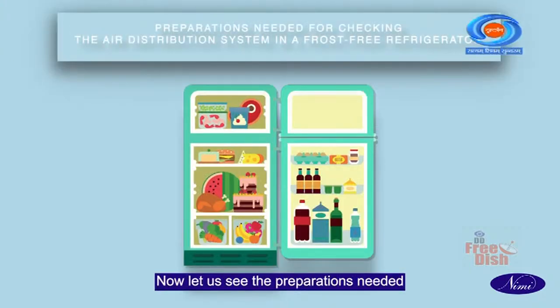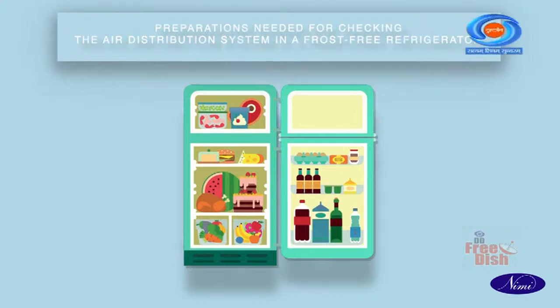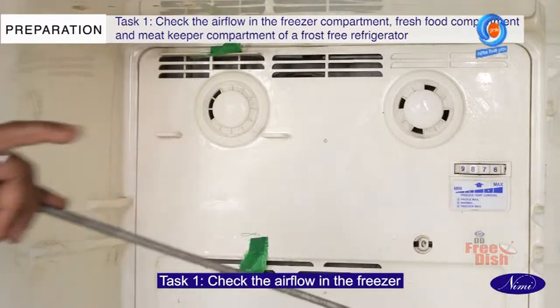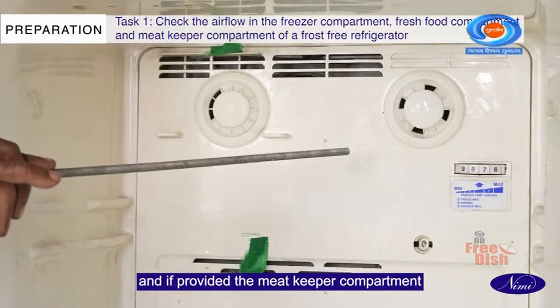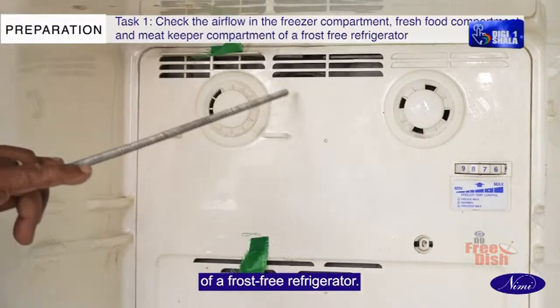Now, let us see the preparations needed for checking the air distribution system in a frost-free refrigerator. Task 1. Check the airflow in the freezer compartment, fresh food compartment, and, if provided, the meat keeper compartment of a frost-free refrigerator.